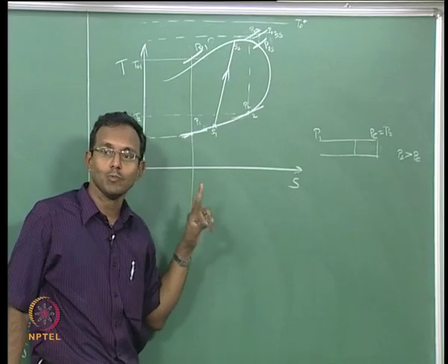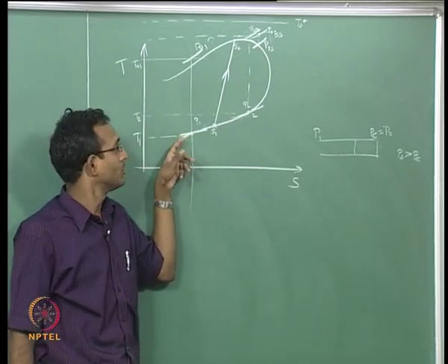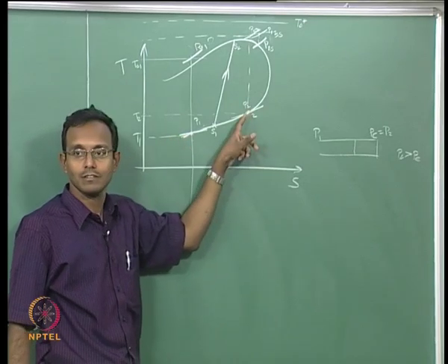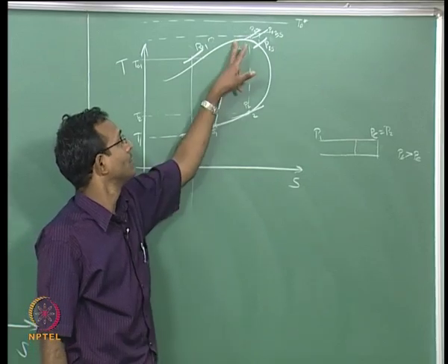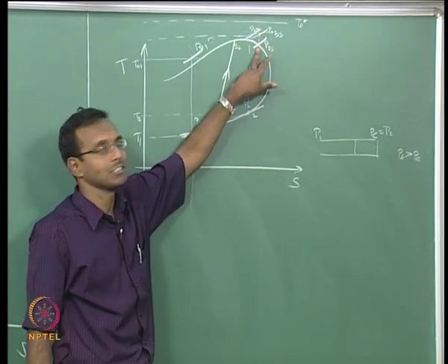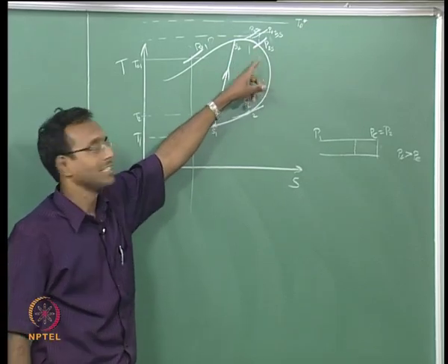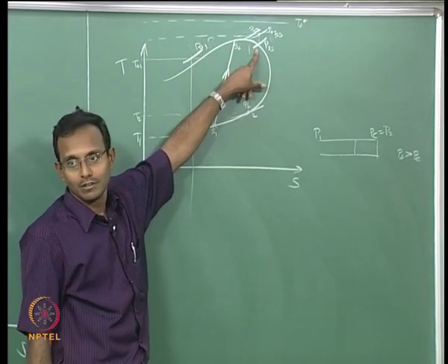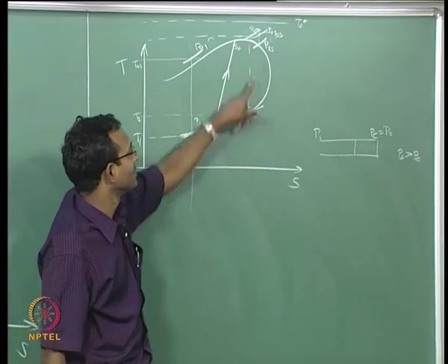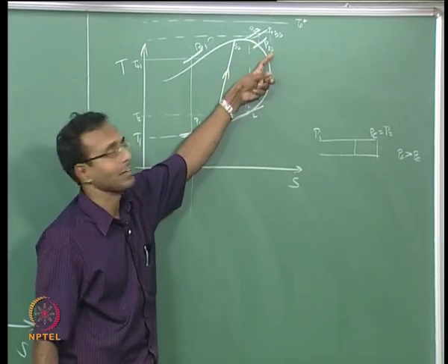So, I can have two possibilities when I have supersonic incoming flow. I can go through just a full supersonic path all the way with the same amount of heat, or it can have a normal shock such that it will match the pressure and sit somewhere else out there. Okay. If I had some other pressure, let us say the pressure is such that it is a lower pressure value, let us say it is between this and this, what will happen? I need a curve that is closer to this line.